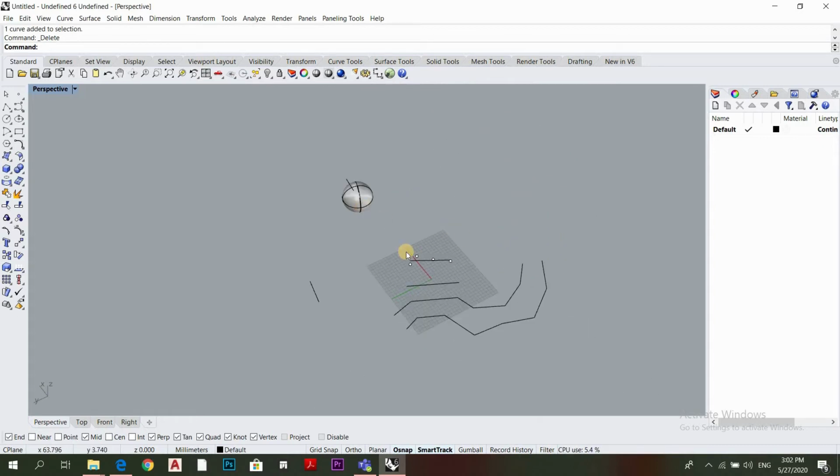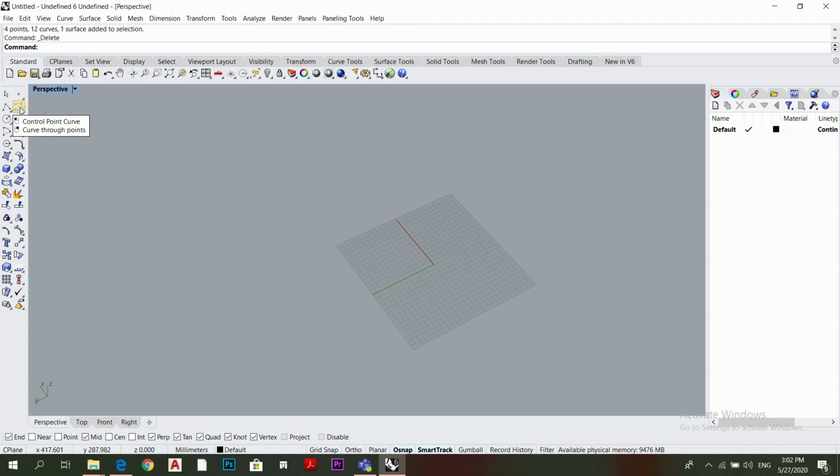So, moving on to the next part, which is curves. Let's just delete these. In general, in Rhino, in some commands, you might get the words select curve. Select curve is not just limited to these commands or the shapes you will draw from here. Lines, circles, ellipses, everything in 2D is considered a curve when we are doing 3D modeling.